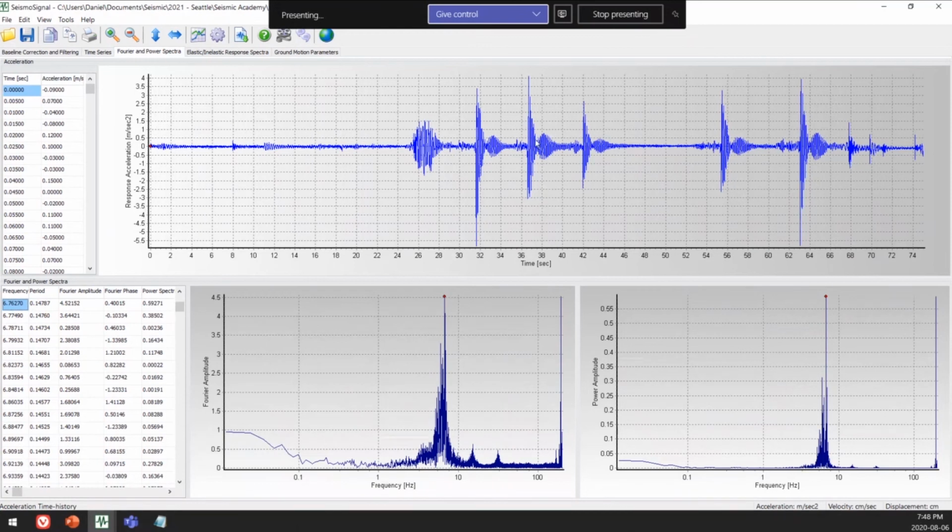There are these weird interferences, and this is because of the torsional asymmetry of the tower. The mode shape isn't as nice. It's not like a simple cantilever. It's rotating. But even then, once you take the Fourier transform on the bottom left, you get this really nice peak right at 0.14787 seconds period, or 6.76 hertz.